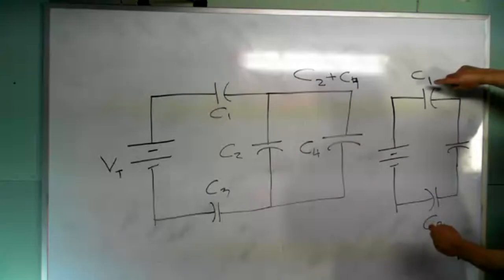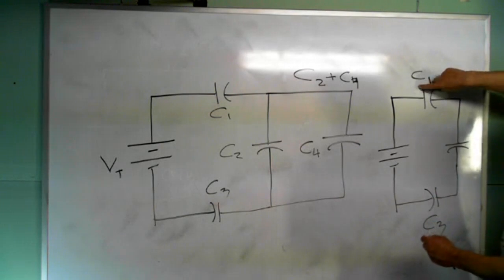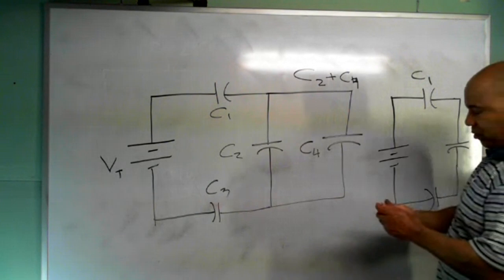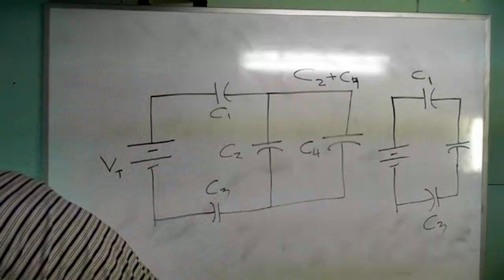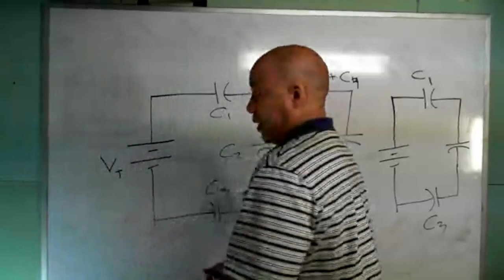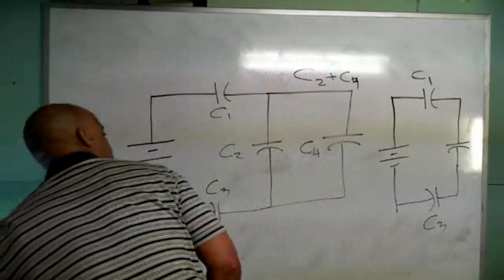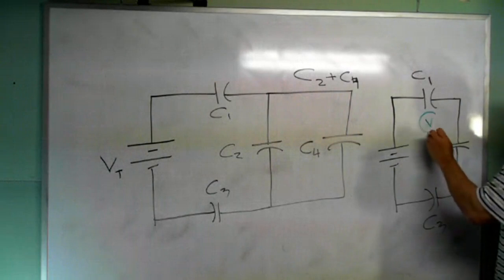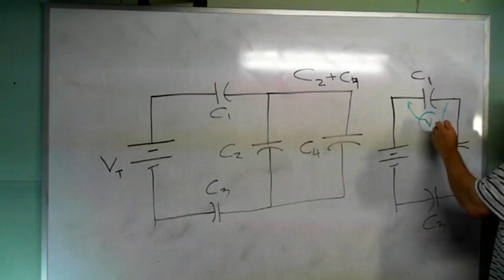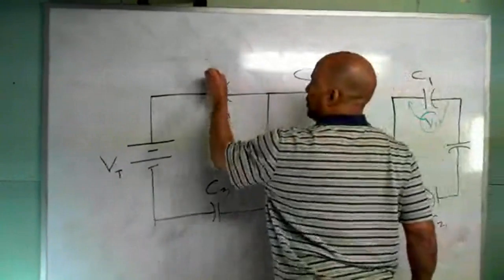And then you would solve this exactly like we did in the problem we just got through doing. What that will do is give you the voltage drop across each of these. So by solving this, you will know the voltage. Let me get a green marker. If you solve that, you will get the voltage across this one, V1, which means you would know this.